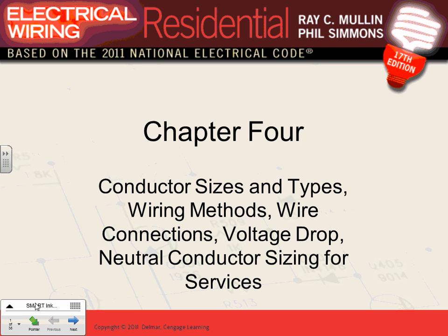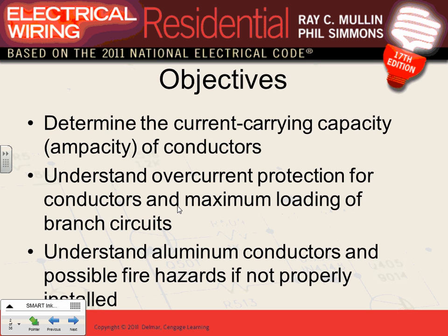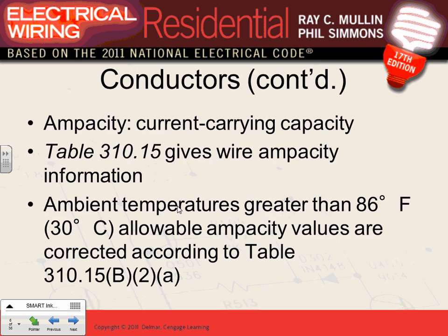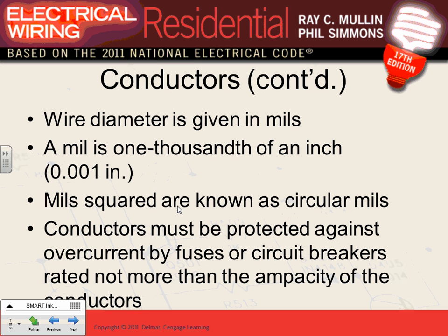Okay, we talked yesterday about table 310.15(B)(16), the derating, and all this good stuff. That was part of what we did yesterday, if you guys remember. We talked about a bunch of other things. Conductors are measured in AWG and kcmil. We went to 310.15 and did the ampacity based on 30 degrees. Everybody's okay with going to 310.15(B)(16) and finding the ampacity based on the rules of the 60, 75, and 90? That's very, very important, what we did yesterday.